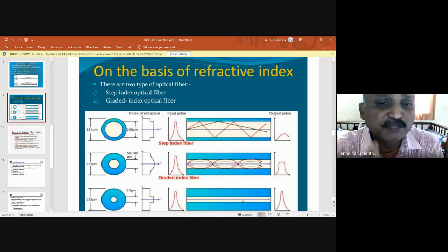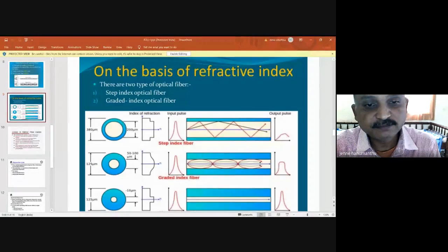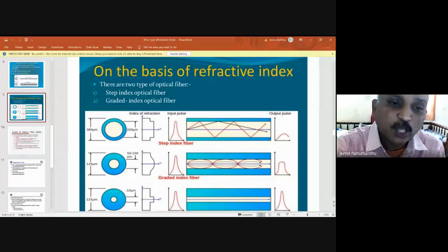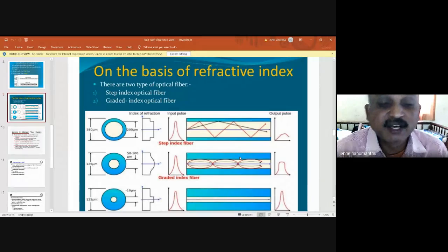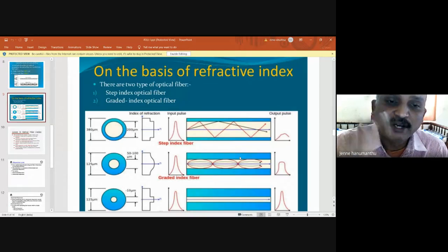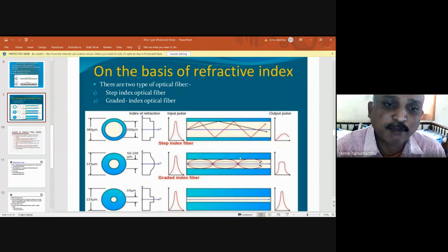The light is simply leaked, that enters into the atmosphere. The light is radiated. Understand? So this is the fourth loss occurring while light is being transmitted. Understand my point? Because of the connectors, because of the splicers, the light may be lost. This is also one more loss.